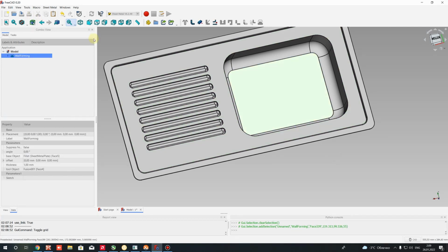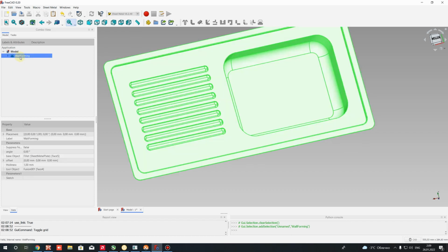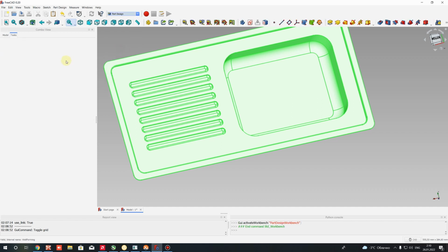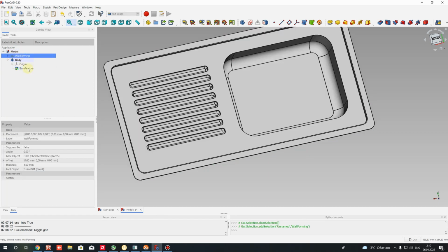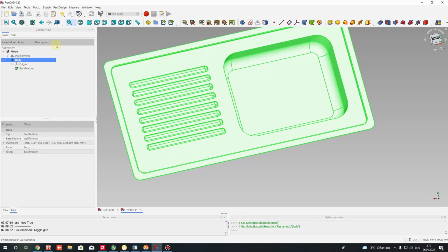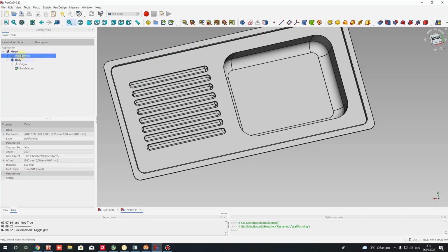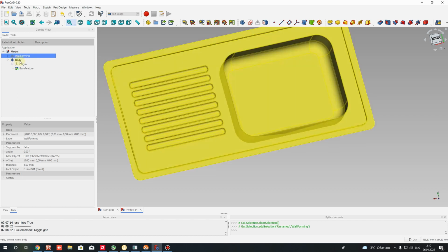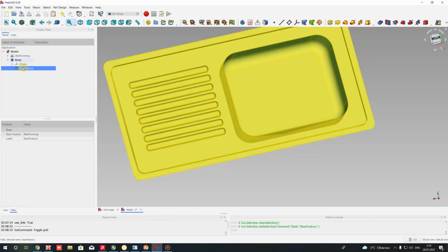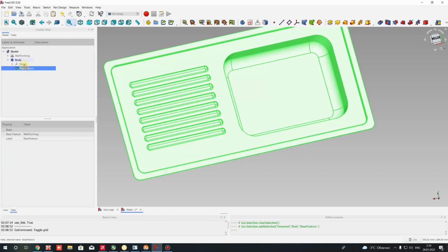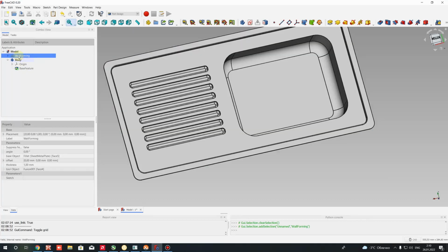Let's create holes, and we can make holes in part design workbench. Let's activate the part design workbench. Let's choose wall forming. Let's go here and click create body. Let's go to model, and how can you see that we import this like a base feature to part design workbench, because I choose it in the tree before I create a body of part design workbench. And now I can work with this body which linked with this wall forming here.